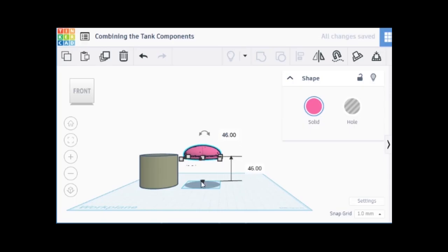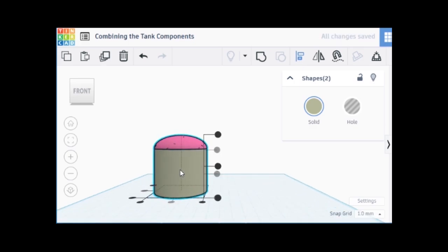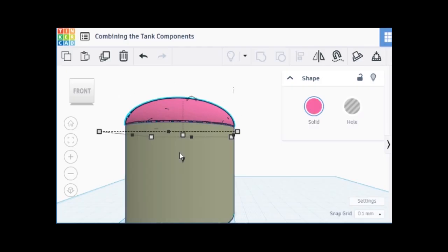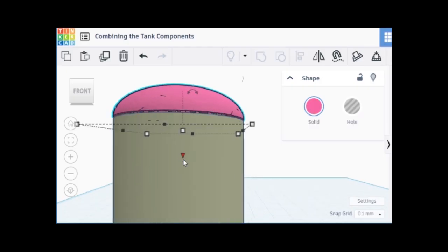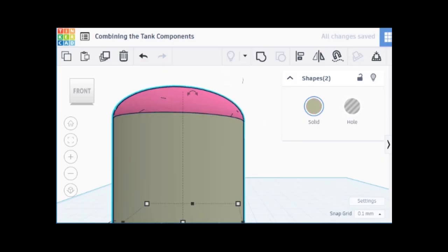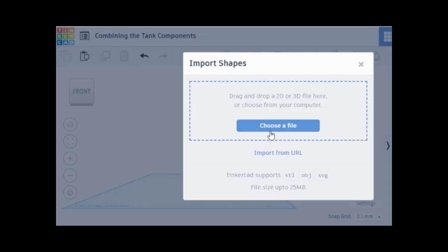I probably will alter the snap grid resolution to 0.10 millimeters and fine-tune the elevation of the topper. Finally, I group them prior to exporting and printing. Depending on whether this is a contest piece, I may print it at a layer height of 0.08 millimeters or 0.20 millimeters. I specify slim tree supports in the slicer.